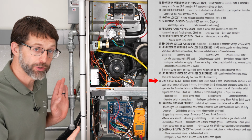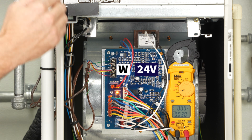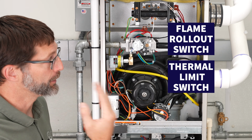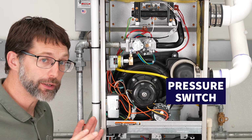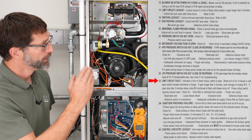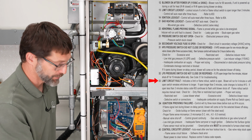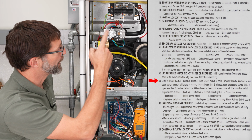And here's the thing, with a gas furnace, if you have a call for heat on the W right here for your thermostat wire, and you have 24 volts there, the furnace, before it's even going to turn this inducer motor on, is always checking to see if a limit switch is tripped. It's checking for that, it's checking for flame rectification, it's checking to make sure that the pressure switches are open. It's doing these checks before it even tries to turn on. So this error code number 33 could happen while the system is running. And it could also happen, say, if the furnace is off and it's showing you that there's a problem with one of your limit circuits, such as thermal limit or flame rollout switches.